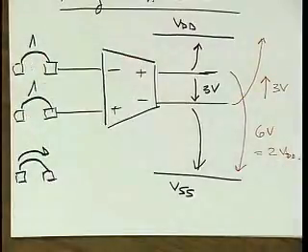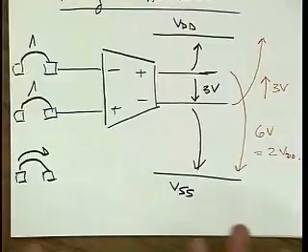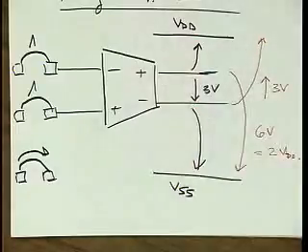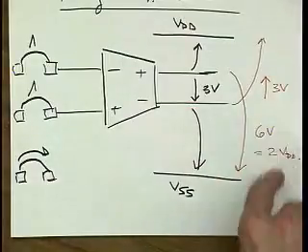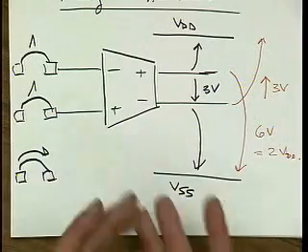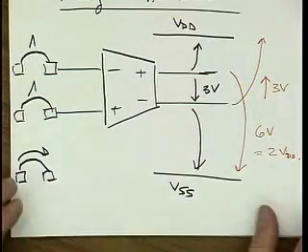Okay? Well, we just doubled the signal power and we didn't do much to the noise. So we ought to win 3 dB. Right? So the fully differential amplifier has a noise advantage on top of everything. Of course, usually we don't quite get 2 VDD, but with the single-ended we also don't get quite VDD. So that all works out.